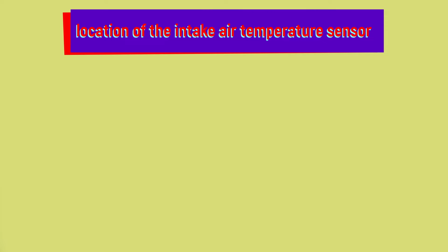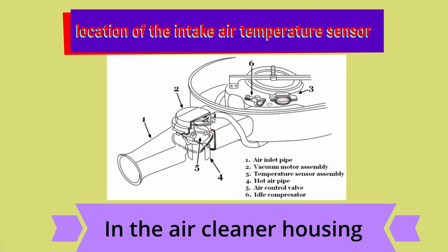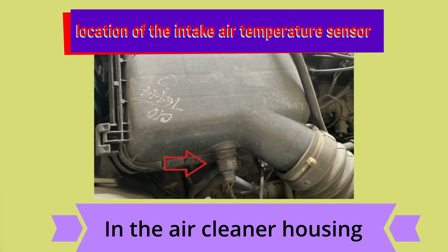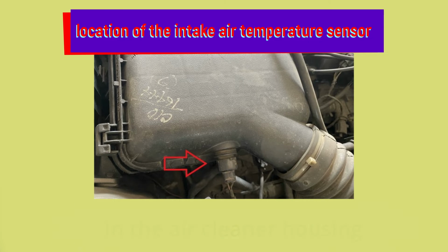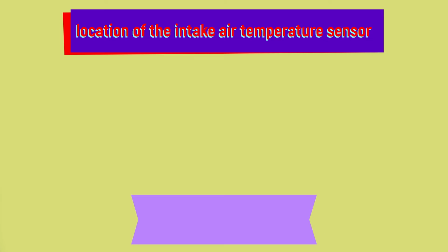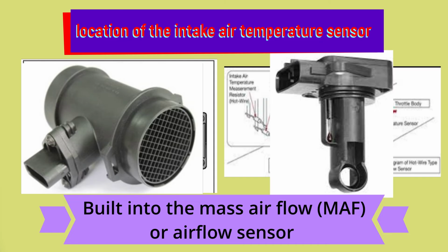The intake air temperature sensor can be located in one of the following locations. In the air cleaner housing, in the air duct between the air filter and the throttle body, built into the mass airflow or airflow sensor.